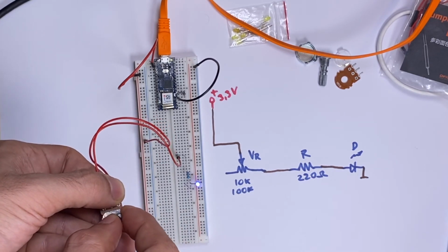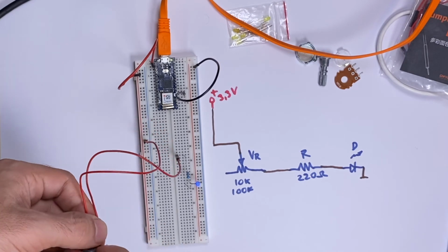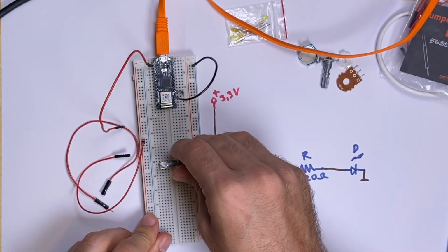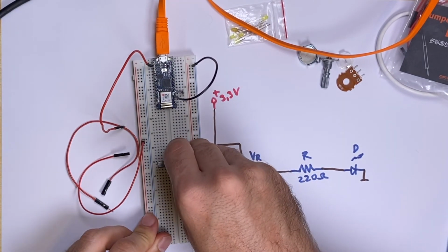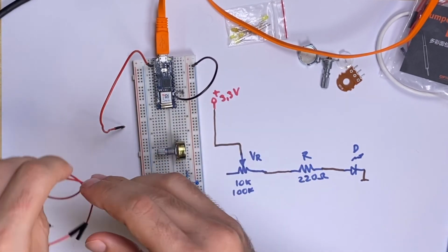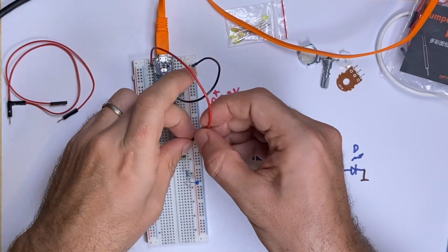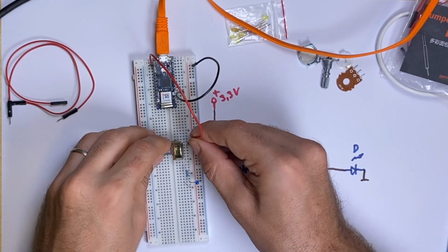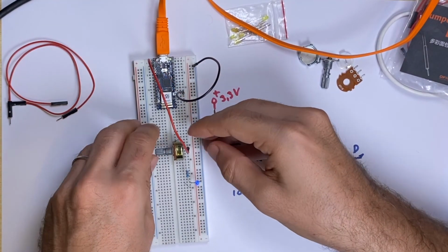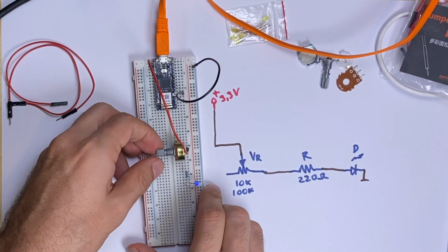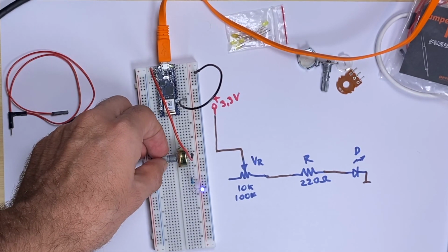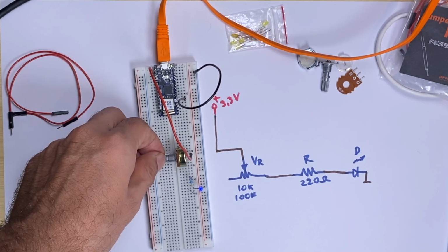Of course, the other option is to connect the potentiometer directly to the breadboard. I think that in my case, it will work as well. Inserting it into the breadboard might be okay for some of you, as I was saying. Then you need to pay attention where the terminals are and to be placing the cables correctly. The range will depend highly on how big the potentiometer you are using is. In my case, it turns quite smoothly, and I chose to use one of 10,000 ohms.